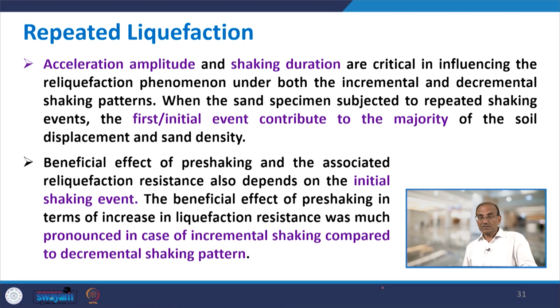So, the summary of the results which we have discussed: acceleration amplitude and shaking duration are critical in influencing the reliquefaction phenomena under both the incremental and decremental shaking pattern. So, it will depend on your amplitude, number one, and shaking duration. The larger shaking duration will provide more settlement as well as more pore pressure ratio. Similarly, the higher the amplitude of acceleration, it will provide higher values, which is expected.